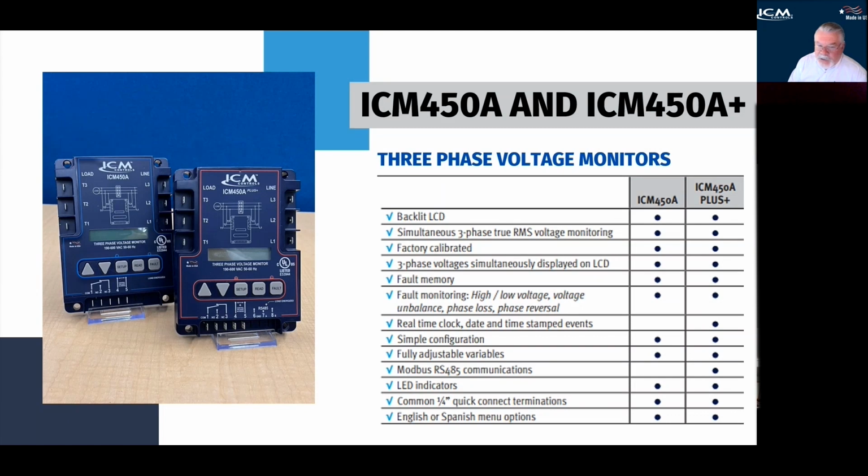So that's been a nice feature add as well. LED indicators tell you what's going on. And we changed the connection terminals to these quick connect terminals, like a spade terminal. So you can put an insulated spade terminal in there. A couple of different things can happen. First of all, you can reach in there with the screw type terminals and get bit by electricity if you're not careful. But you can also short some things out if you're not careful with those open exposed terminals. So this is a safety feature and just problem solver, kind of a headache solver.